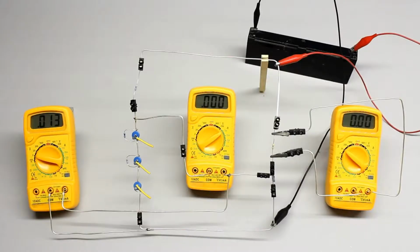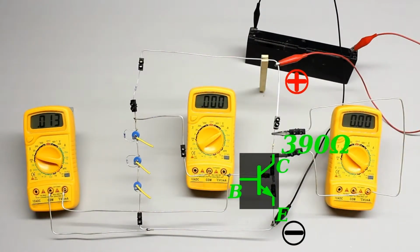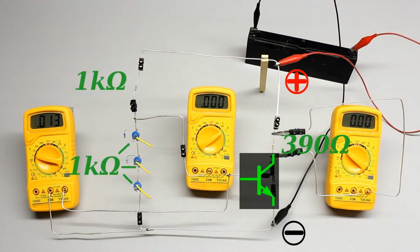The emitter pin is connected to the negative terminal. The collector is connected to the positive terminal via a constant resistor of 390 ohm. A voltage divider is formed by 3 potentiometers and 1 constant resistor of 1 kiloohm, so that a variable voltage can be attached to the base pin of the transistor.